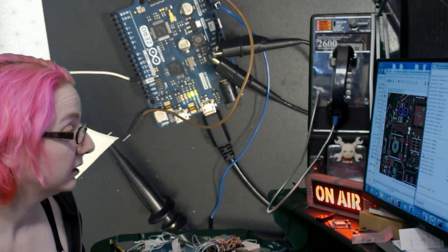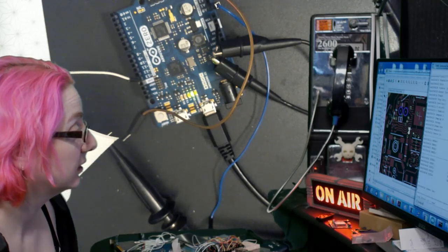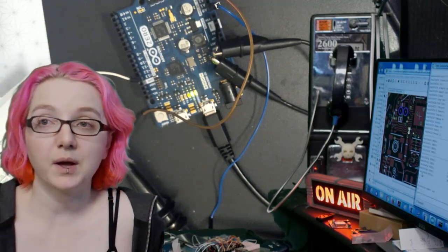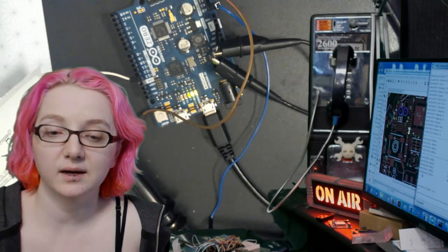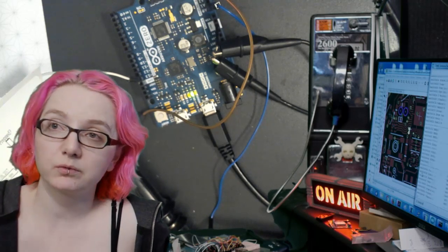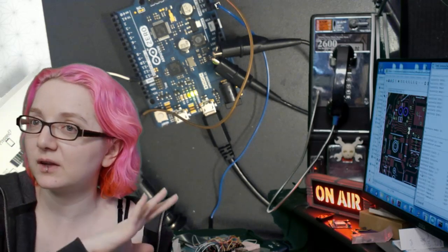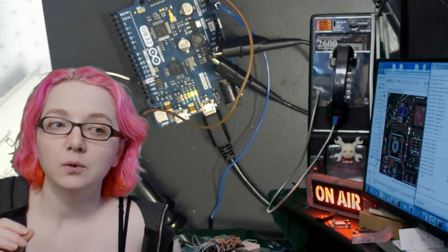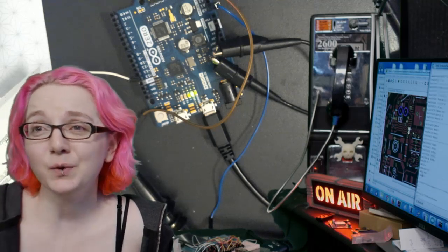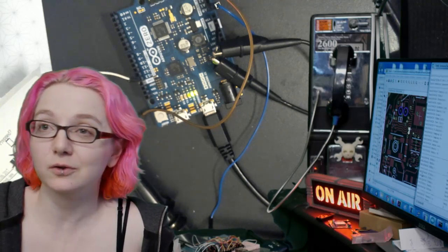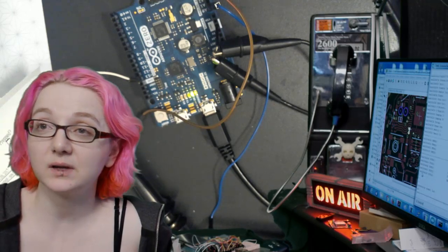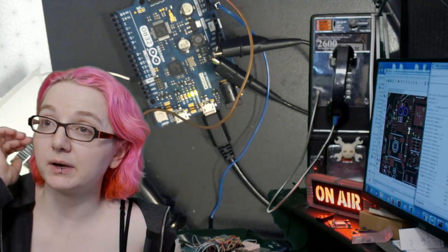So far, some good success with the QTOUCH reverse engineering. Next up, I'm going to just clean it up and make it prettier. And then I'll get rid of all of the library code. Right now I'm using the QTOUCH library for initialization, but not for reading. What I'll do is get rid of that initialization code too and see if it works. If it works even half well, it's still better than doing the resistor trick and better than linking an external library. And then I'll probably post it up on GitHub or maybe write a little tutorial on how to use it.